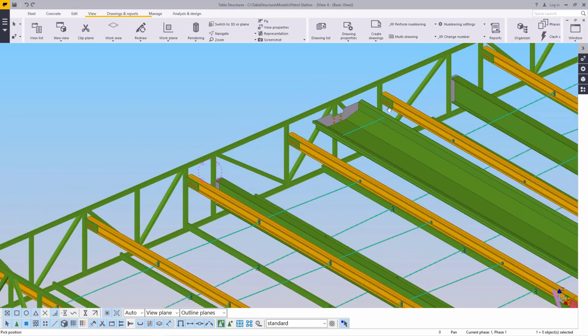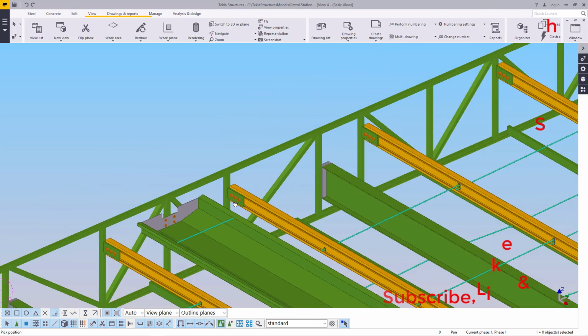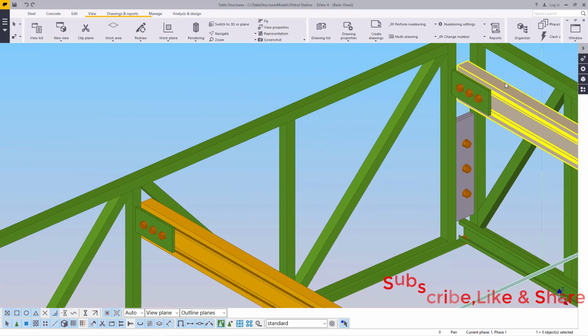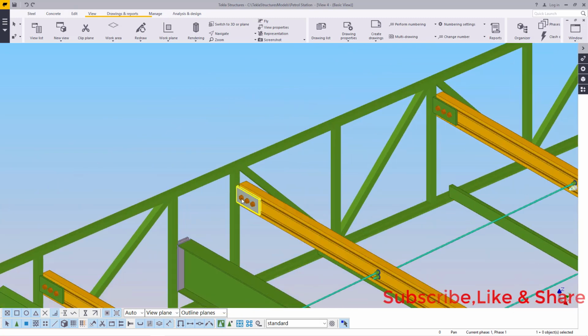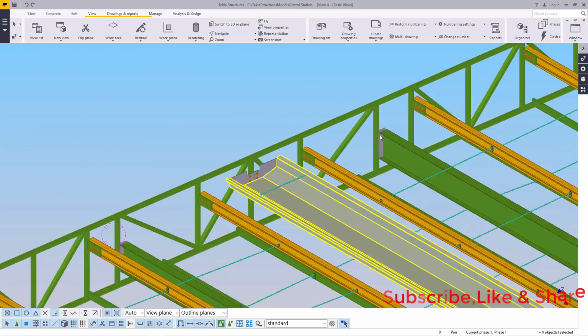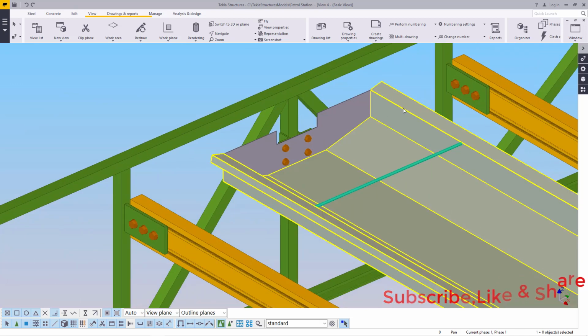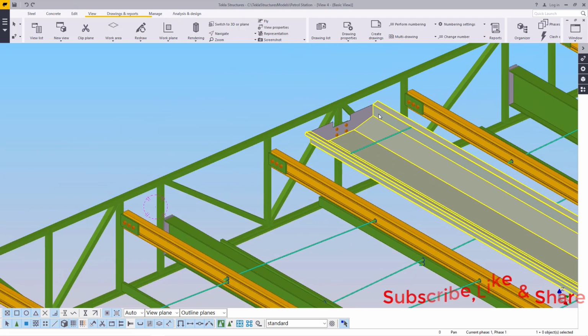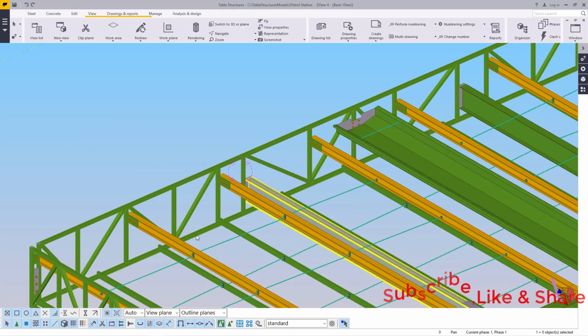So first of all, let me just finalize with the connections of the pilings. At the end here, you can see we have a cleat connected there to pilings, we have a cleat there, and we have a cleat here. And you can also see at the end of our valley gutter, we have a plate at the end here just to create a stopper for water flow, just to restrain the flow, not to move out of the defined path that is called the valley gutter there.